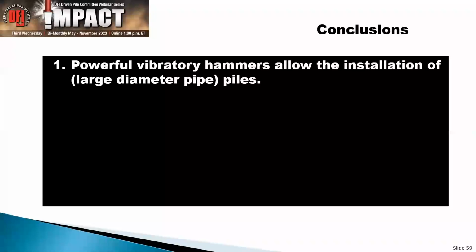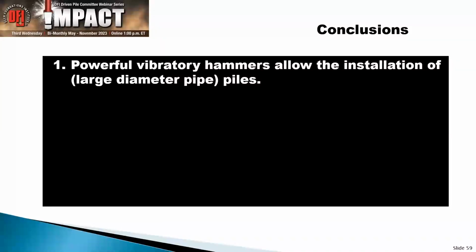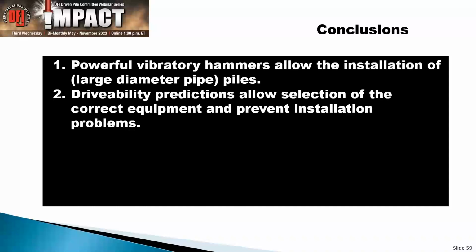So what are the conclusions? Why am I so excited about vibratory hammers? Because you can get large diameter piles. If I talk about a pile, what we did in Hong Kong, a 72 footer in the ground, you cannot do that with an impact hammer.